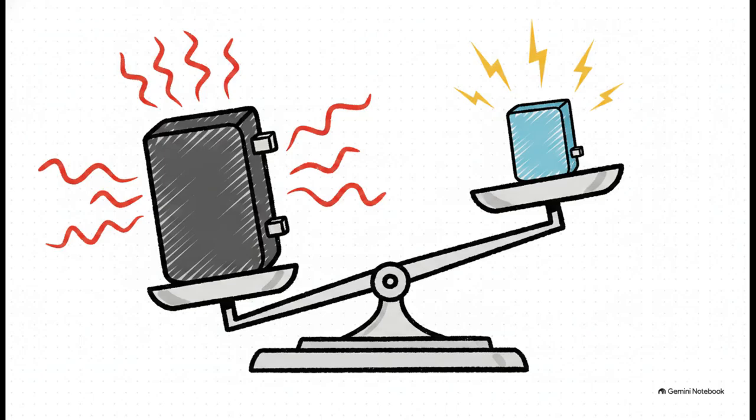Now, you might be looking at that and thinking, well, a 2% efficiency bump at 60 watts sounds pretty small, right? But because GaN generates far less waste heat, thanks entirely to that wider band gap, it requires far fewer bulky thermal management components. So the real-world consumer benefit is honestly astonishing. A GaN charger is literally half the size and half the weight of a comparable silicon charger. We are talking about a twofold reduction in volume and weight, coupled with higher power density. That tiny 2% efficiency bump literally translates into that incredibly tiny brick you now carry around in your backpack.